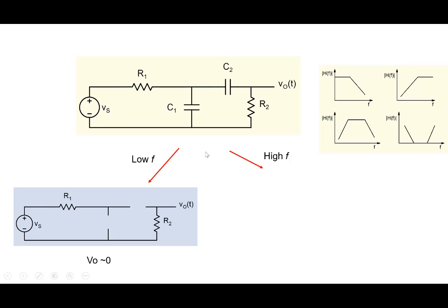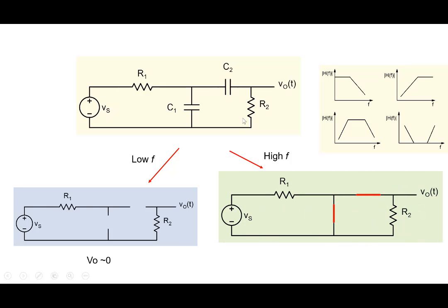All right, what about high frequency? At high frequency the capacitors act as shorts. So this is a short, this is a short. And what happens to V0? Because this is a short here, V0 is again 0. Right, so I'll leave it to you.